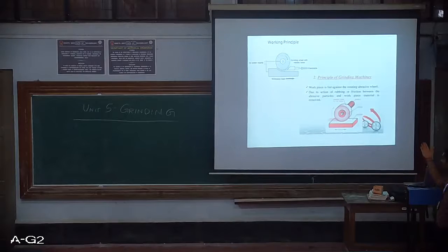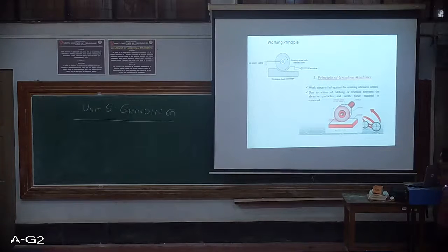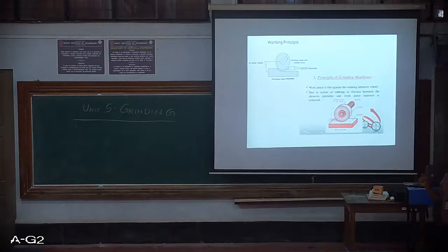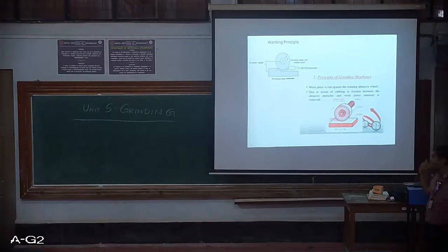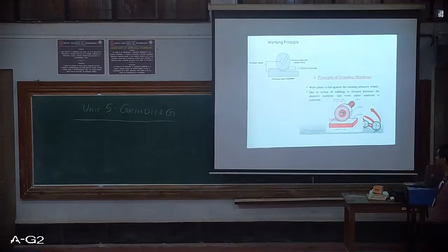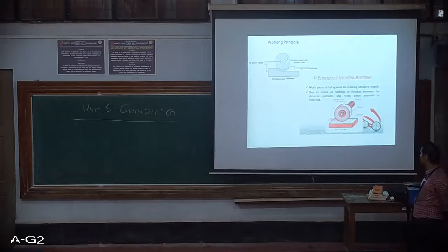So the grinding wheel is attached with the metallic bond, that is your abrasives and bond. Then you have a power supply, right? And you have an electrolyte that is fed in between the work and the tool, and the work is fed towards the right direction. Okay, this is that 3D diagram I was talking to you about. So you can see how the grinder or the unit is actually performing its action.